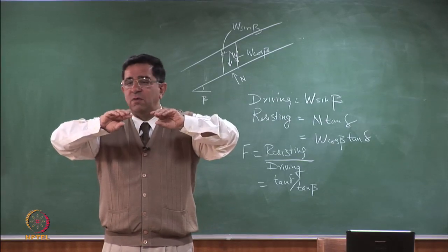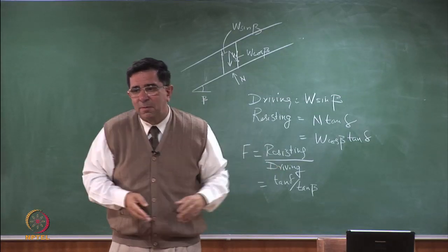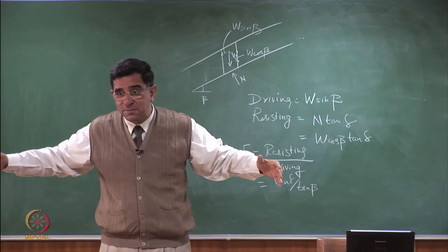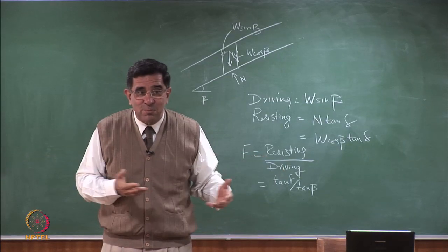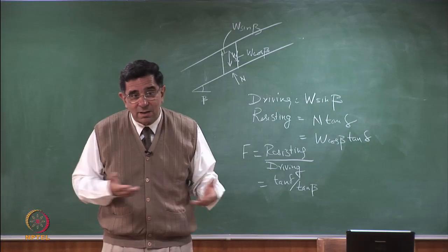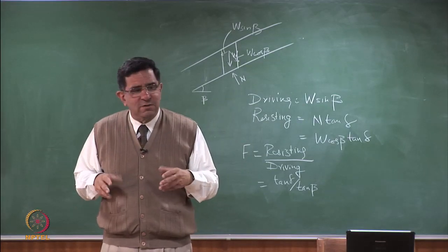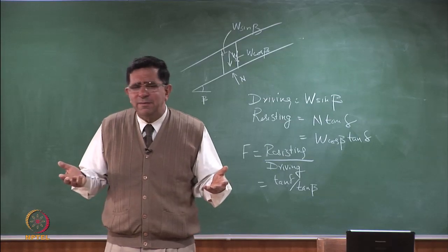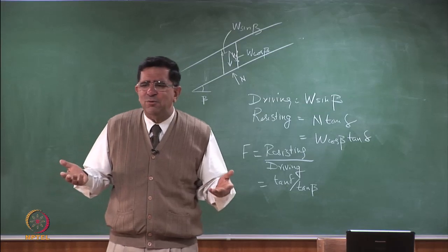You see, what's a cover failure? A cover failure, the topsoil will slide down. But if the whole landfill slides, that's a much bigger failure. And do remember that you are putting the landfill on a geomembrane. And designers like us have originally been saying the base is flat, so let's have a smooth geomembrane, or maybe it's only tilting at 2-3 degrees,